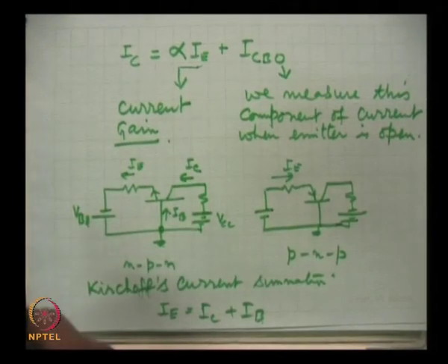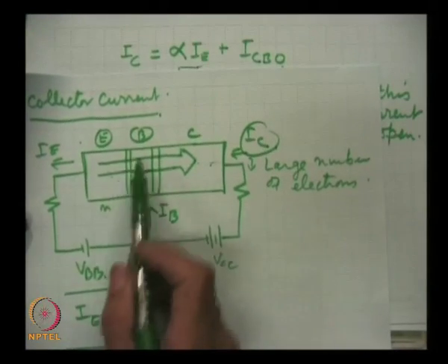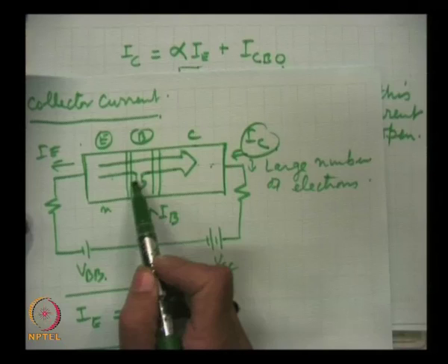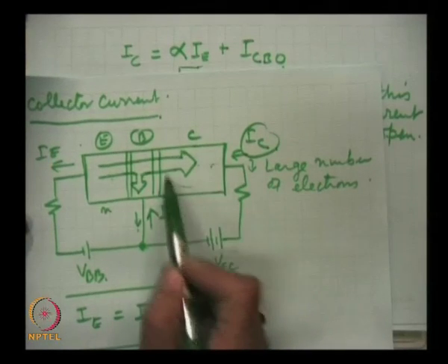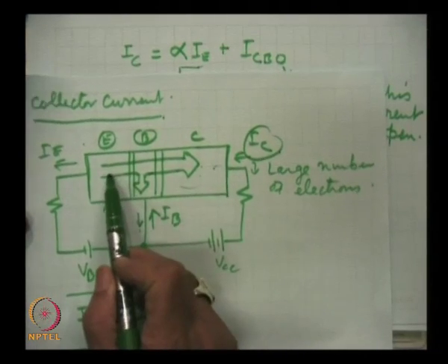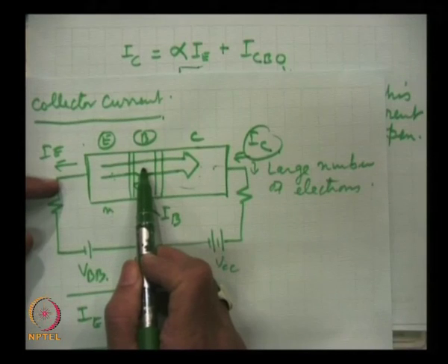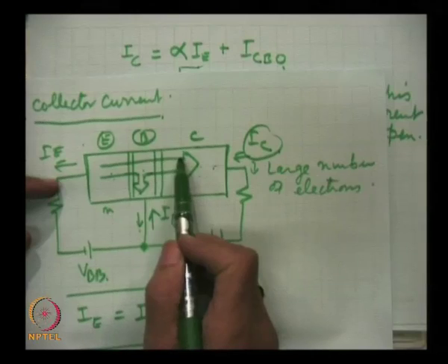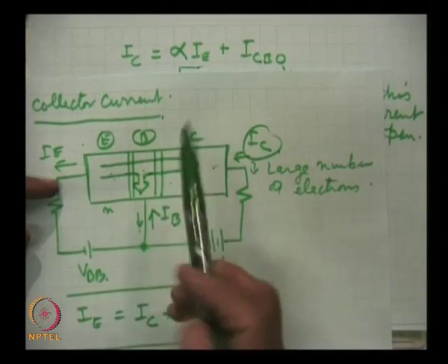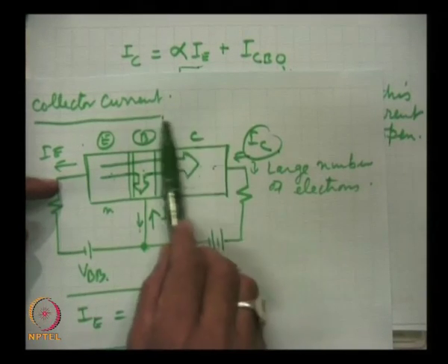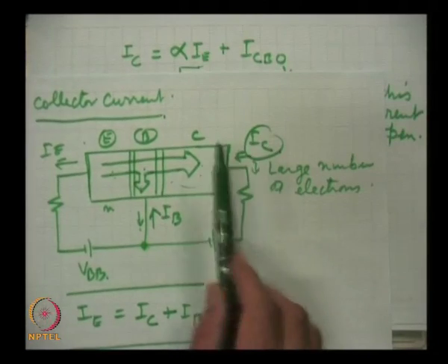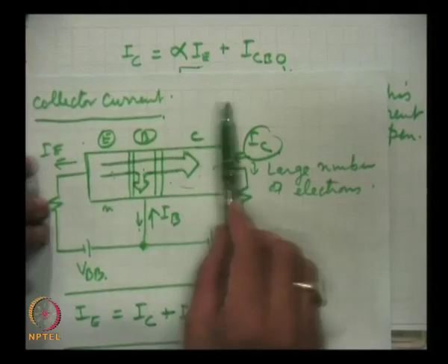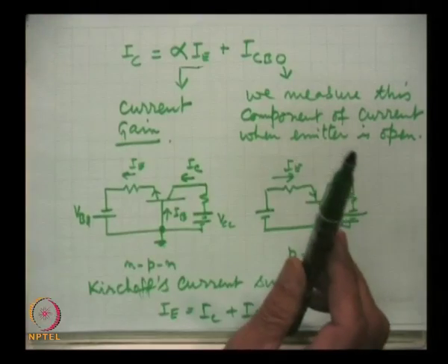The emitter of a PNP transistor will be very rich in holes, with very small density of electrons and very high density of holes. The holes from here will be injected, a percent or so will recombine with the electrons, and the remaining ones will diffuse, and as soon as they reach near the electrode, this favorable potential will collect them.